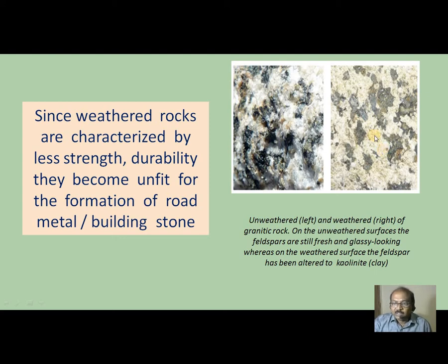In unweathered granitic rock, the feldspars are still fresh, whereas the feldspars are altered to kaolinite, that is clay, in the weathered granite part, which is shown on the right side. That's why strength becomes less, durability also becomes less. Hence, weathered rocks are unfit for the formation of road metal and also building stone.